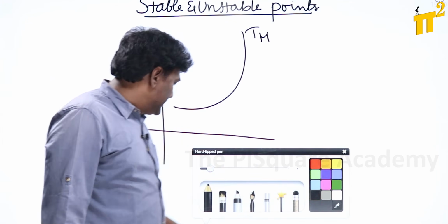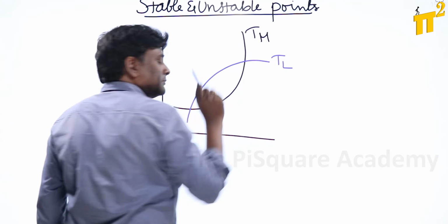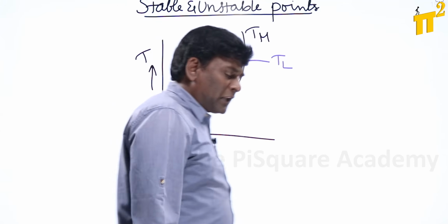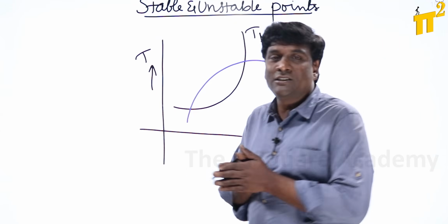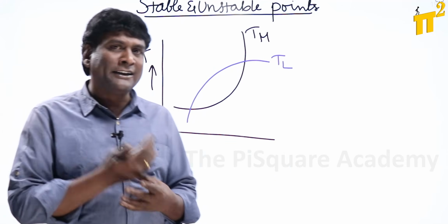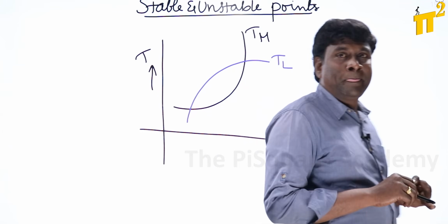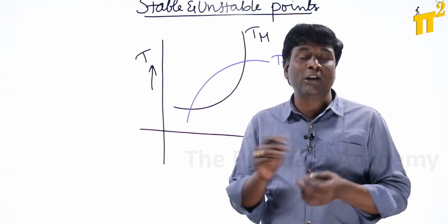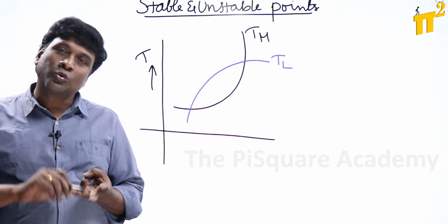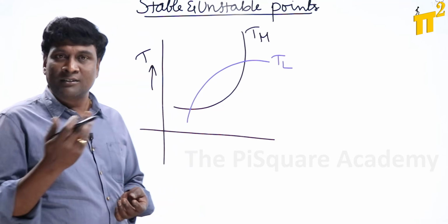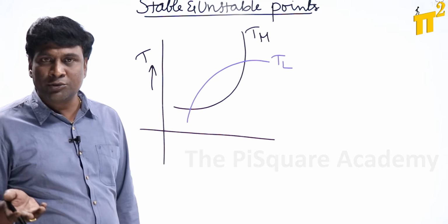Okay, if I think of this as the torque requirement of the load, I need not say that the torque requirement of the load is always constant. For example, for solid to solid friction, the torque requirement will be constant, like metal cutting tools, as I have said multiple times. For solid to liquid, the torque requirement will be directly proportional to speed. And for solid to air, like a ceiling fan or fan load, the torque requirement of the load will be directly proportional to speed square.